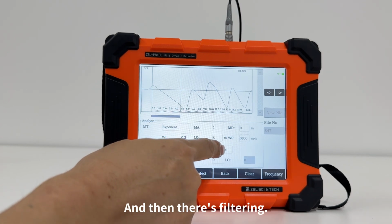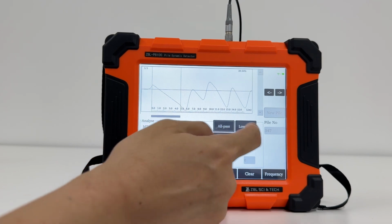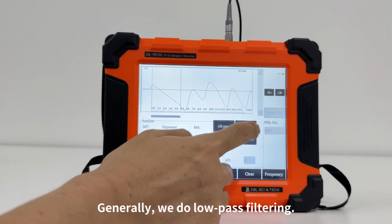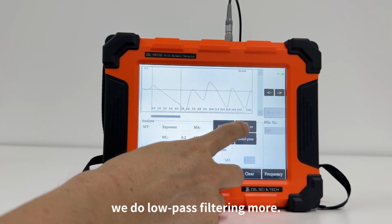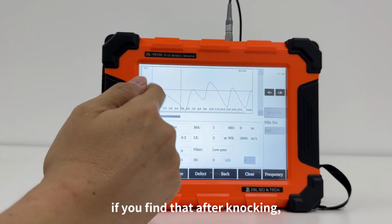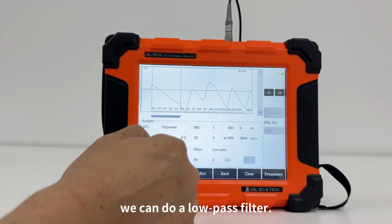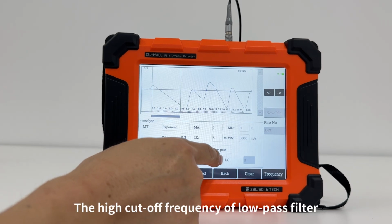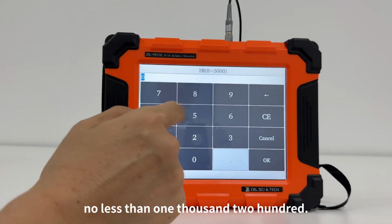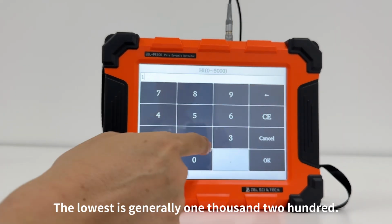And then there's filtering. The filter types include low pass, high pass, band pass, and no filtering. Generally, we do low pass filtering more. If you find that after knocking, the waveform has many spikes, we can do a low pass filter. The high cutoff frequency of the low pass filter is generally not less than 1200. It's all above 1200. The lowest is generally 1200.